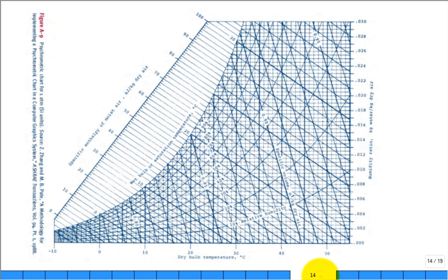Let me jump over here. So there's 33 right here, isn't it? 33 dry bulb. What was the relative humidity? 30%. Right there's the intersection. We're not going to try and do this too carefully or too accurately. We're going to get 2 significant digits, and that's about it.